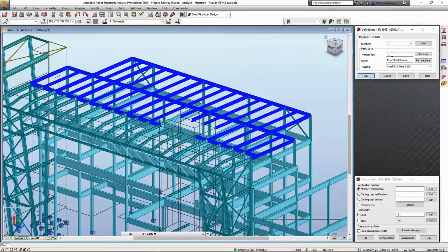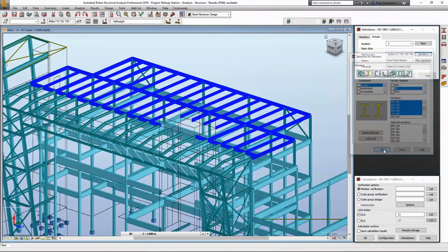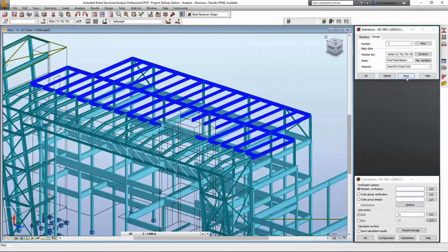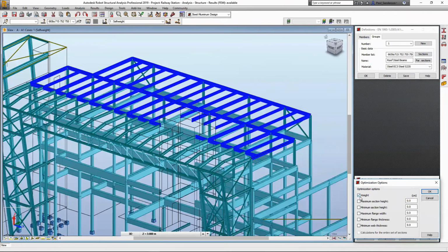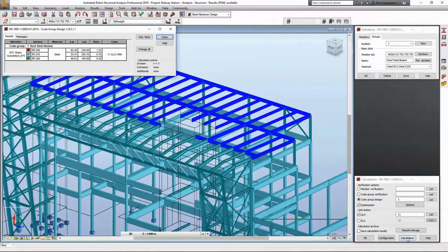And the reason for this is the ability that Robot has to quickly generate the steel members and update the Revit model itself. In this case here, we're updating those beams to an IPE steel section. It's basically just selecting the beams that we needed to update. As I showed you previously, we would group it so that when we apply a change, it changes the entire group instead of working on individual components.